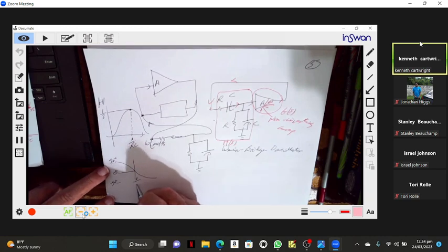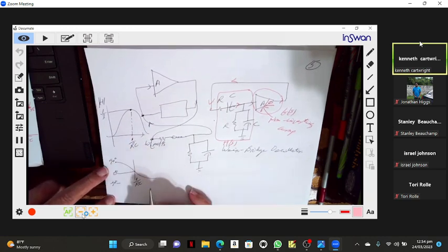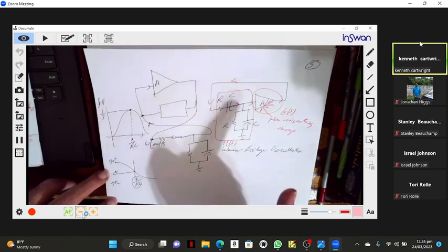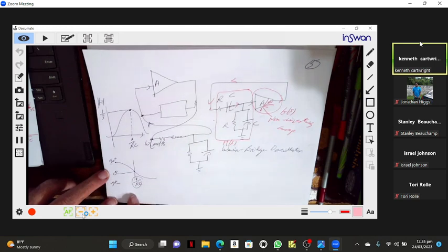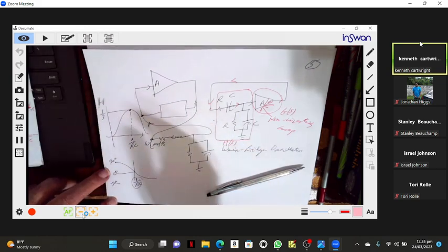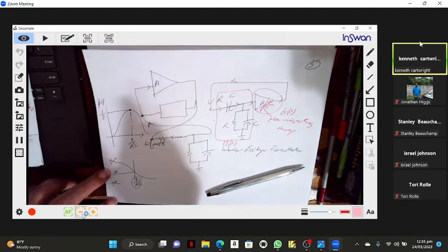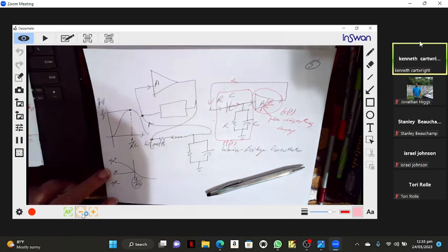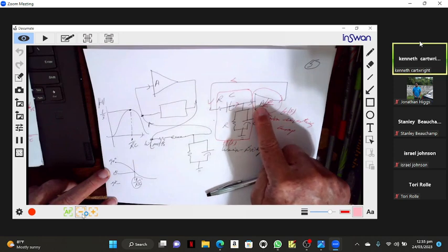At this frequency, 1 over RC, we have a phase shift of 0 degrees, and that's what we're interested in. So if this thing is going to oscillate, it's going to oscillate at 1 over RC. But that is not enough to say that we're going to have oscillation. We need two things for oscillation. We need the phase to be right, and we need A to be right.